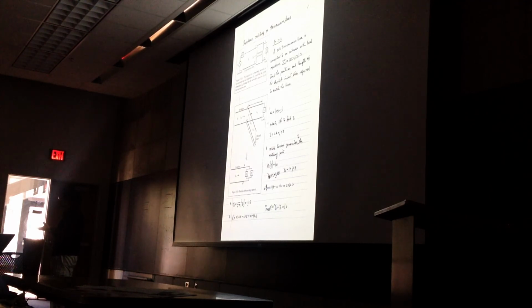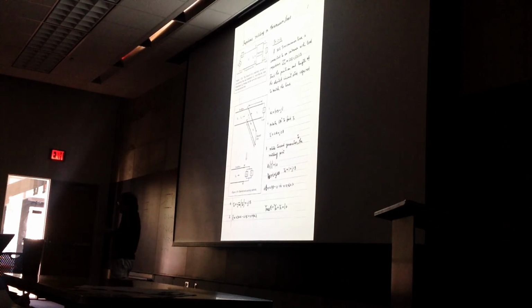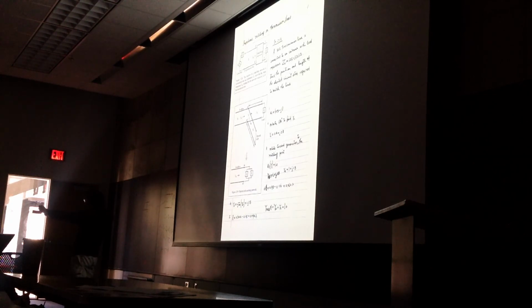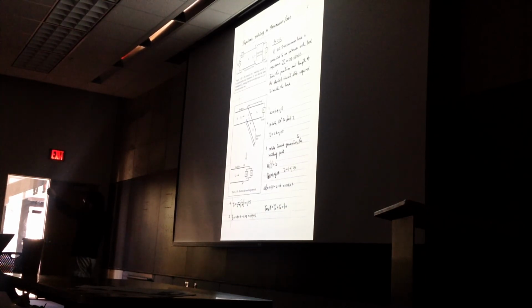Exactly. Think about it. What is an inductor? Have you ever looked at an inductor? It's really just wire. So to some degree, it's really not magic. You just take your wire in a different way. Again, you can think about this as a coaxial cable. I adjust the coaxial cable to be 0.062 lambda long, and then I shunt my coaxial cable in here, and that becomes an inductor.